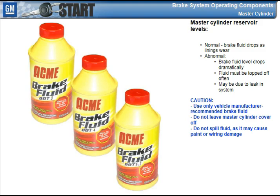Use only the type of brake fluid recommended by the vehicle manufacturer. Using the wrong fluid may cause brake fluid to boil or component failure, leading to loss of braking. Because DOT3, DOT4, and DOT5.1 brake fluids readily absorb moisture from the air, do not leave the master cylinder cover off any longer than necessary. Remember that DOT3, DOT4, and DOT5.1 can damage paint and wiring if spilled. Exercise caution.